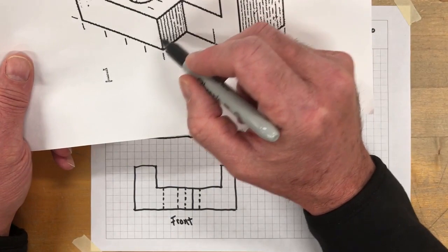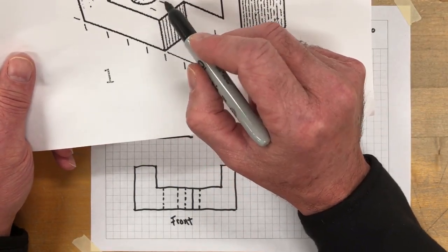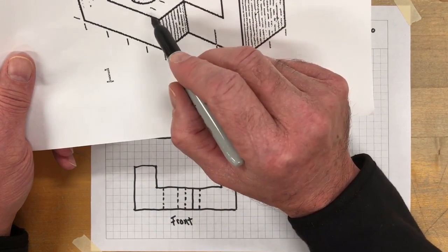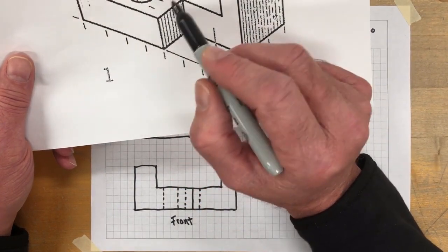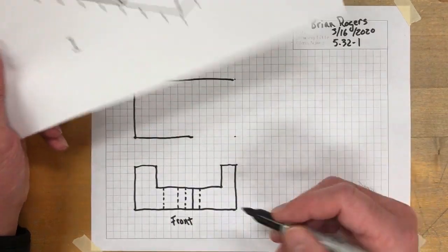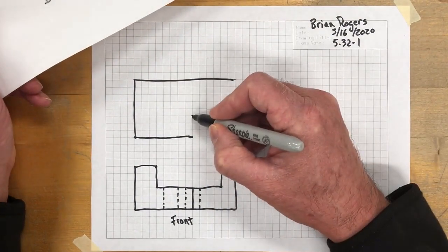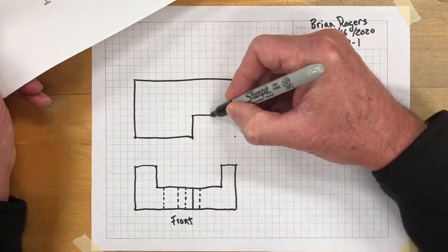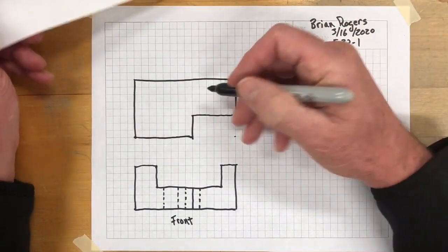But I need to know what the depth of this is, so I take a look up here. I see these small tick marks, 1, 2, 3. Now, as I'm counting these, people, remember I'm counting the space in between, not the actual lines themselves. Okay, so 1, 2, 3/4 of an inch. So 1, 2, 3. And you see now I can go ahead and close this thing up here and create a polygon. Okay, closed polygon. All right, so there's that.